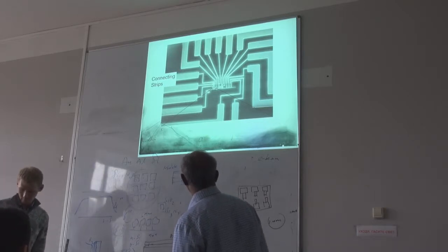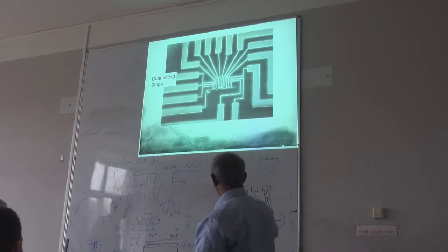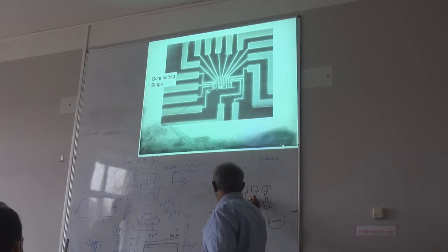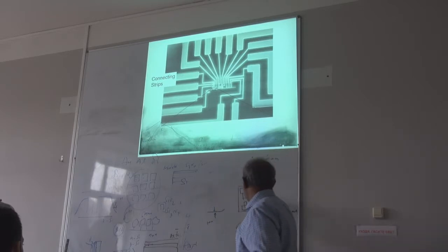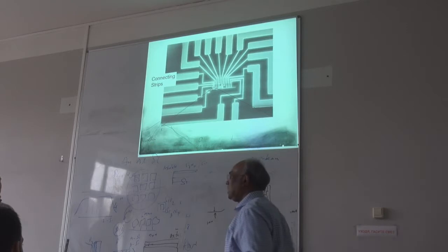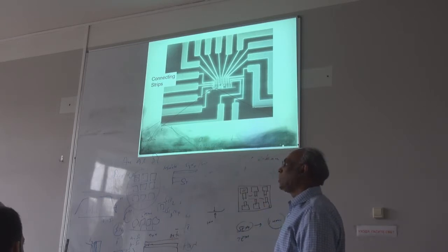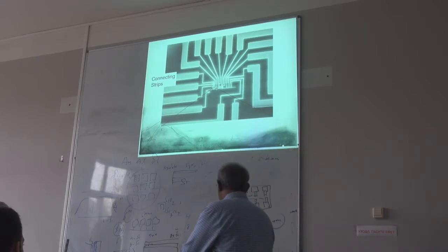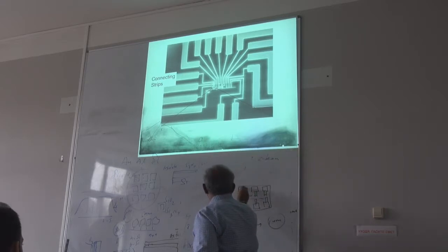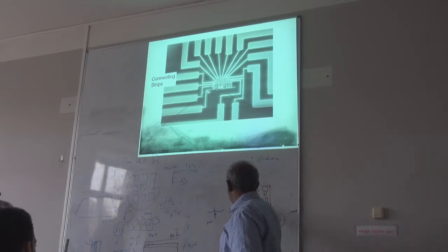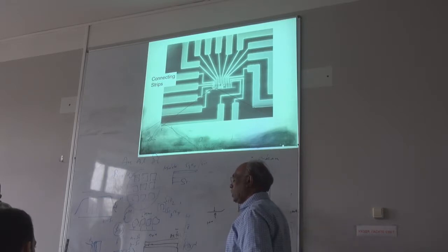Then we take that substrate and grow carbon nanotubes. So what you have is something like this, or maybe something here, or maybe something here. Now I want to make connections to two of these leads, right? For that you have to do E-beam lithography. Since we still have these alignment marks here, we have some idea about the nanotube location.